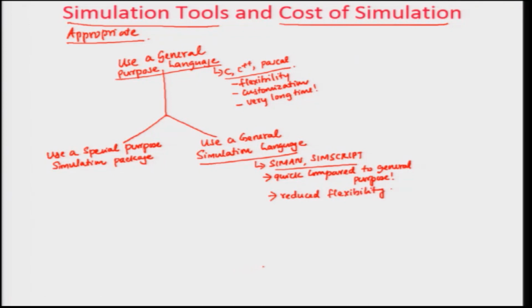Then the last part is that you can use a special purpose simulation package instead of a general simulation language. The special purpose simulation package is more like Arena, Technomatics, etc. These are packages, and the main advantage of them is that they are extremely fast compared to the other two options, but they have the least flexibility.